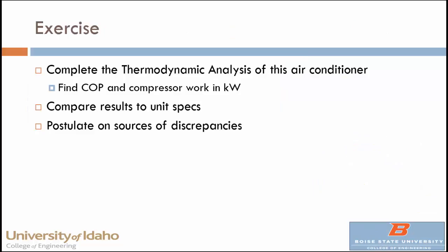And in fact, the problem set for this module builds on this, right? So the first problem in the problem set is to complete the thermodynamic analysis. Find the COP, find the compressor work, find the mass flow rate, but to do that we have to know something that's not just intensive properties, right? We need to know something from the outside, and we do. We can assume the specification for its refrigeration capacity is correct, which is 10,150 BTUs per hour.